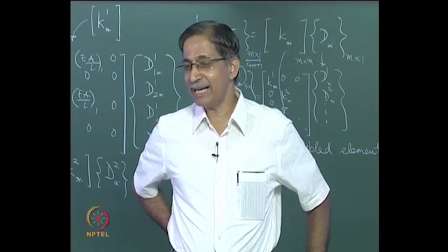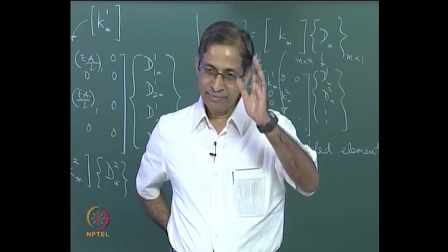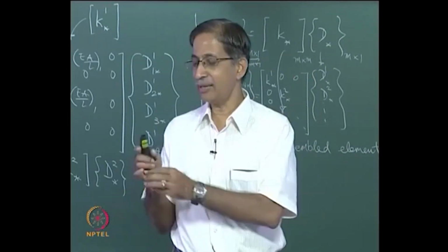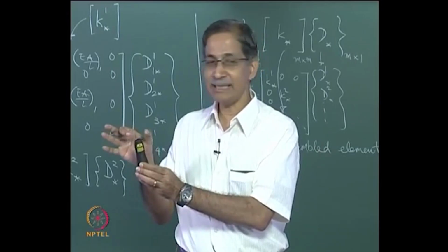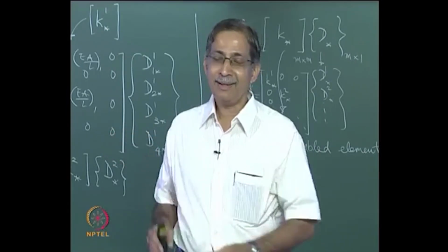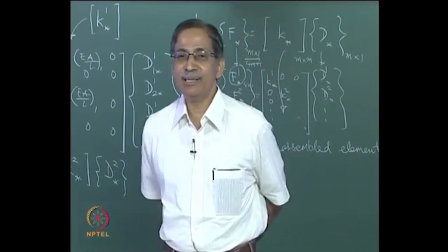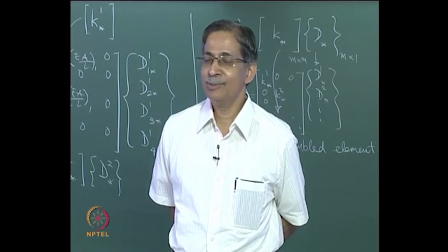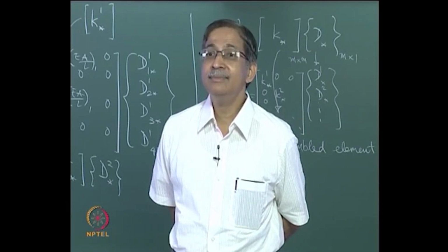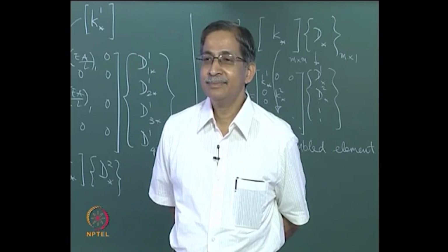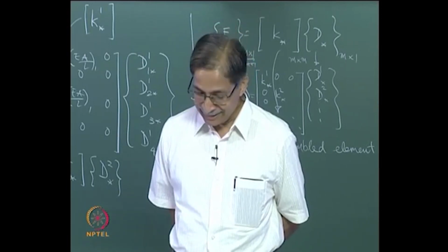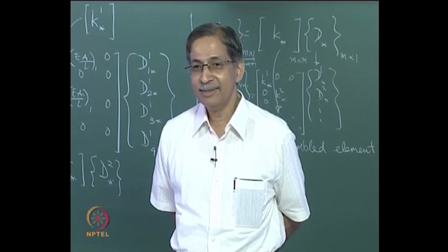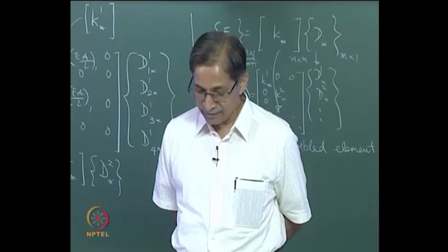The clue is, if you take the flexibility matrix, what does it tell you? If you give some forces, you can find the displacements, right? If I have a structure and I push it, the flexibility tells me how much that deflection is. Now here it will not be able to tell me what the displacements are. Why? You won't be able to. Because there is something when you look at those pictures which should make you nervous when you build such structures. Why are you not nervous? You should get nervous when you look at those elements.